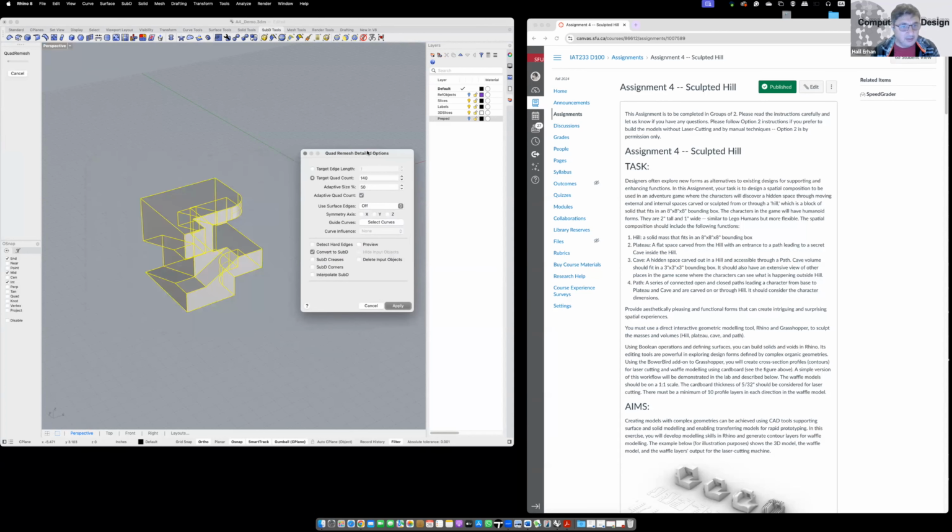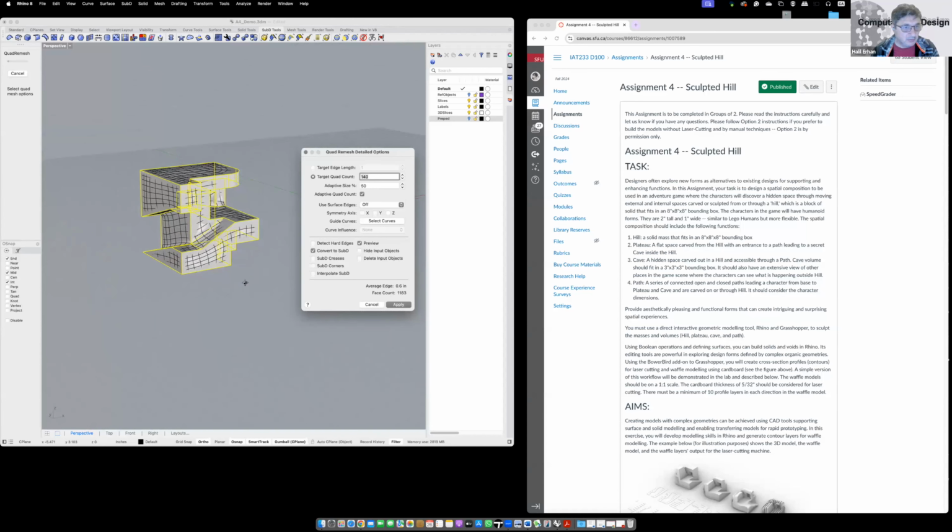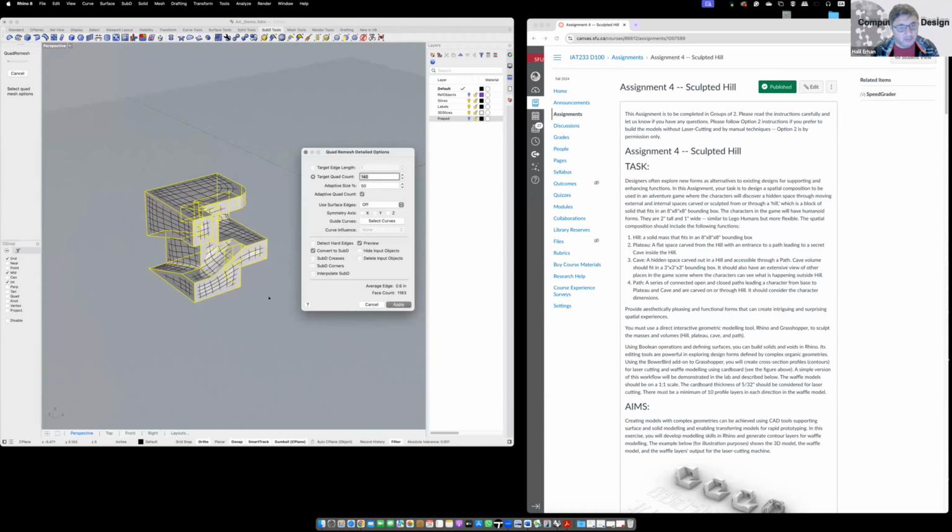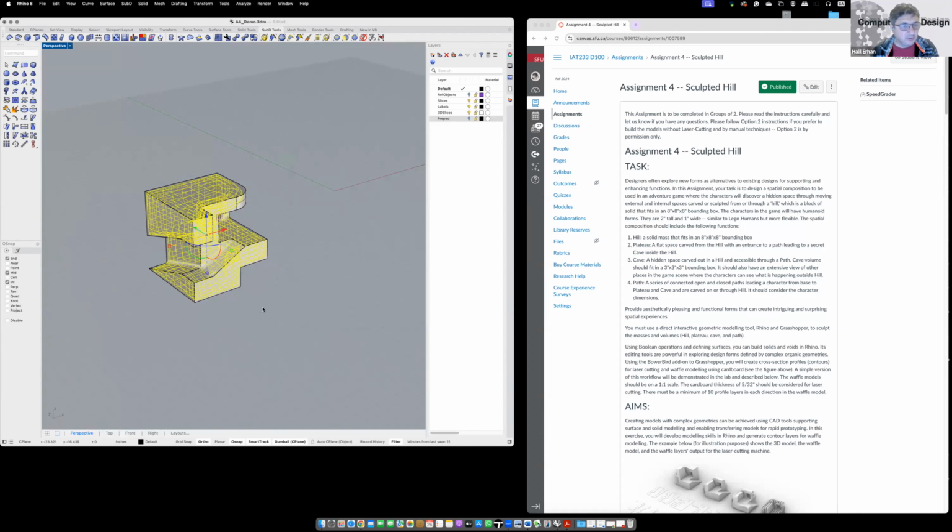Once it is selected, I use low quad count. It comes by default at 2000. Reduce it to 140. It depends how you see it. Let's turn on the view, and we see how it looks, right? I'm happy with this, and I'm going to create this.